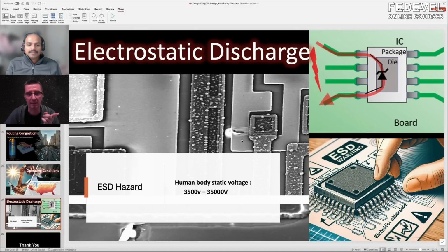There was something else I wanted to mention. This is something many people don't realize. When they are designing boards, they forget that pins are actually connected through these diodes, and in some conditions this can be a problem. For example, when part of your circuit is powered and the other part is not powered, and you are sending out some voltages through signals, they can actually go through these diodes and power the unpowered part of the board.